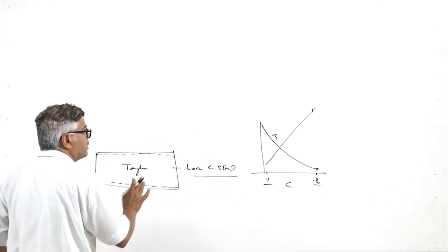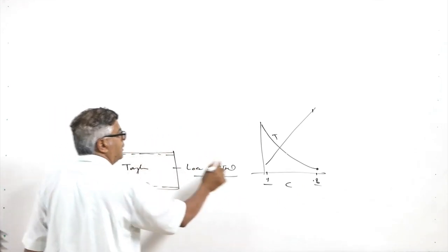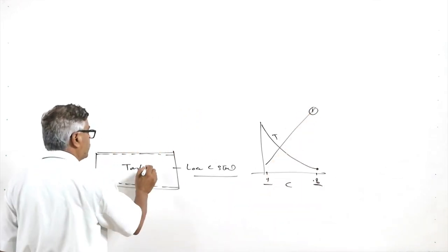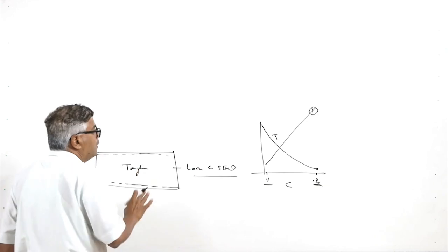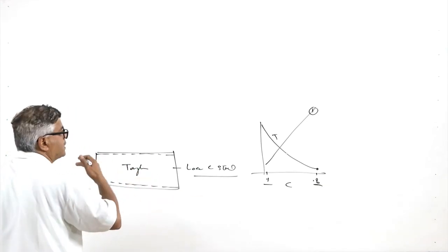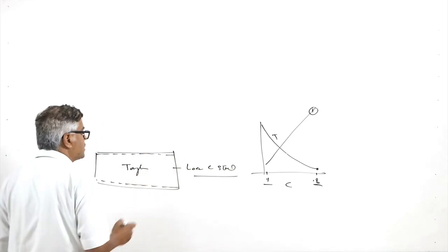So, what combination we want, that surfaces are hard corresponding to the 0.8 level of the carbon content, while the core remains still tough. So, for this purpose only, the core composition is maintained while the surface composition is enriched with the carbon.